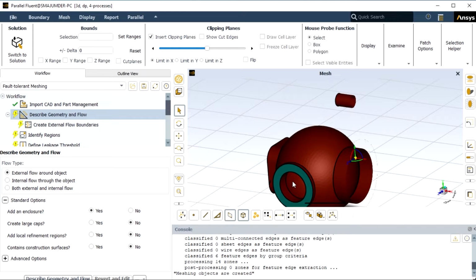So it is a special type of problem. In this case, we will be considering heterogeneous fluid mixing of water, air, and also carbon tetrachloride. At the same time, we'll be saying it is a heat exchanger problem also, because both entries will be having different temperatures and it will be mixed inside the chamber, where heterogeneous fluid mixing will be occurring with air, water, and carbon tetrachloride. And finally, at the exit location, we'll be having the mixture at a specific temperature. Our task will be to find out temperature at the exit location. At the same time, we'll find out temperature, pressure, and velocity distribution at different planes.